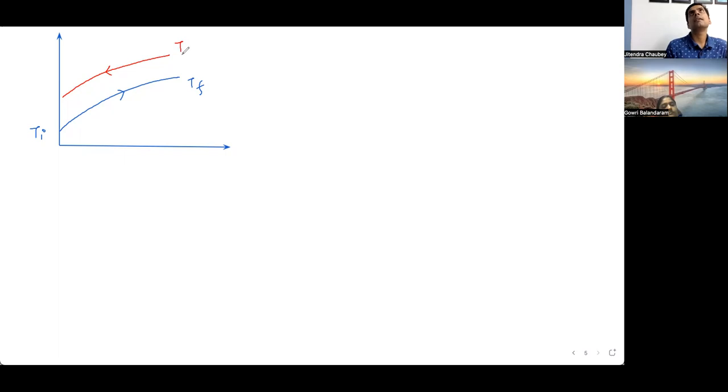So let us say it is T entry and this is T outlet. And they wanted us to find this value, right? Now you need to focus on the required unknown. Because they were asking for this value, we used delta T1. Had they been asking for this value, you would use delta T2. You should know that delta T mean is equal to delta T1 is equal to delta T2.